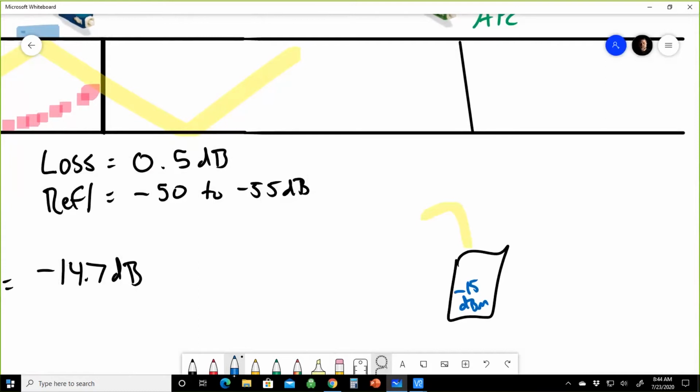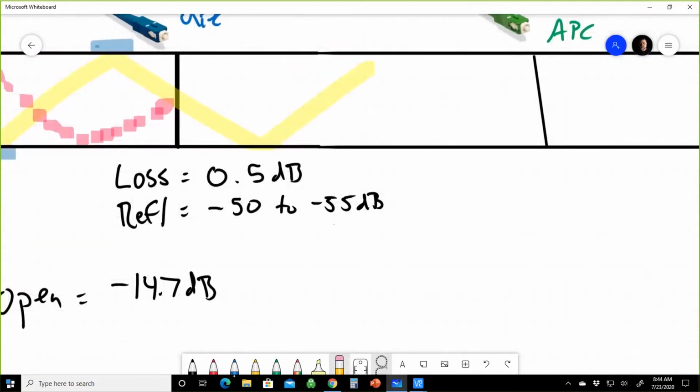You're not cleaning fiber to improve the power. You're cleaning fiber to improve the reflection, right? And unfortunately, power meters don't read reflection. They only read power, right? And if you compare it to water pressure, PSI, water pressure is loss. The quality of that water is reflection, right? So you can have good water pressure, but that doesn't necessarily mean the quality of your water or the taste of your water is very good. And so it's important to understand these two different aspects, because when you look at a system, these are two of the big critical parameters when you're doing fiber characterization, right?